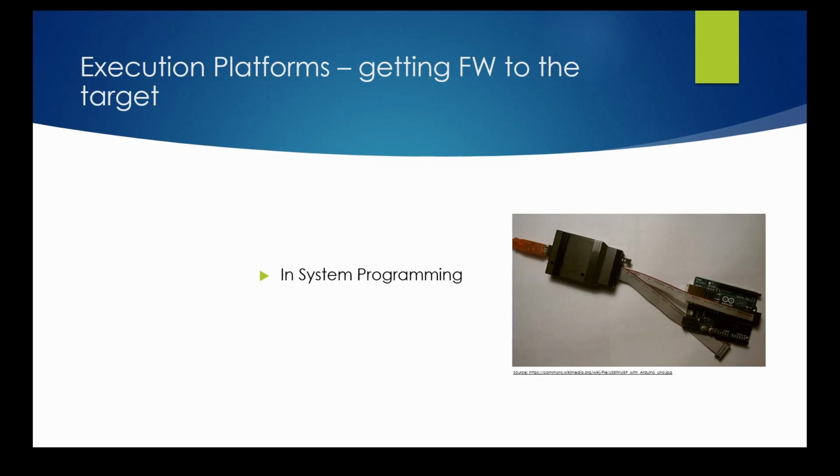Potentially, this method is more powerful than the bootloader method, since a bootloader can have restrictions. For example, a piece of firmware already running on the system may be restricted from writing to certain parts of the storage for security reasons. This is, of course, also the way to get the bootloader into the system.